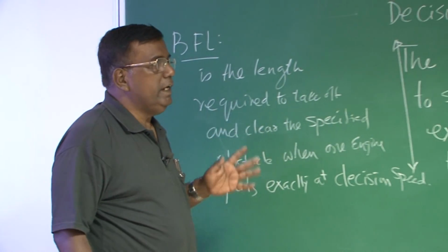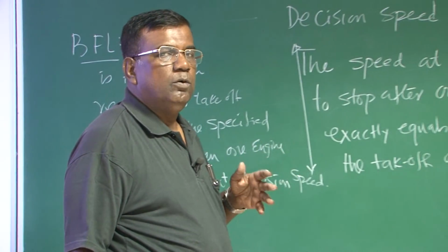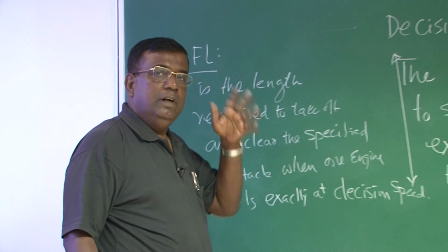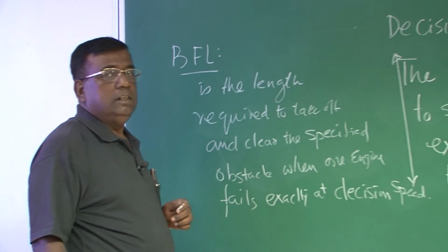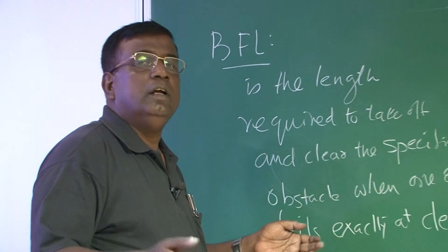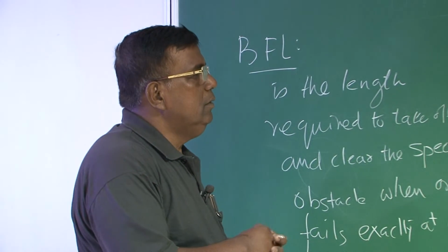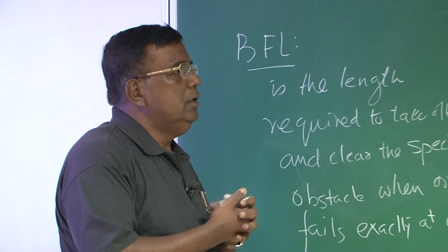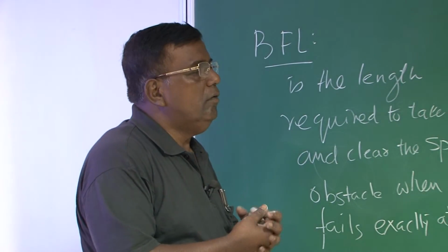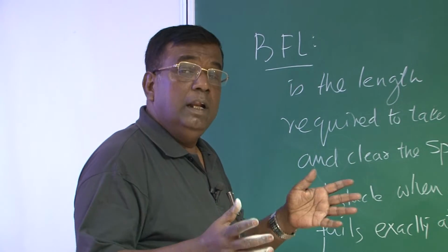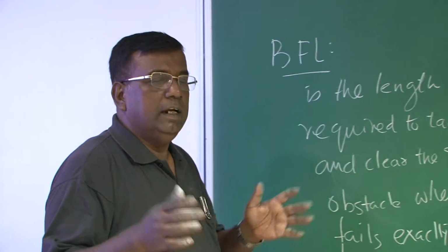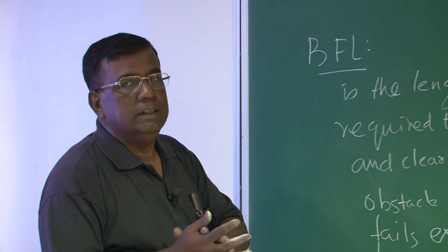If you see my earlier lecture, we have given those parameter correlations for propeller airplanes, and also given how to get the balance field length from those charts, right? However, my advice always would be, because safety has a non-linear requirement, it is better you take data from similar types of aircraft, twin engine aircraft, see what sort of balance field length is prescribed in their manual, get more and more such data and take a decision at a conceptual stage. Thank you.